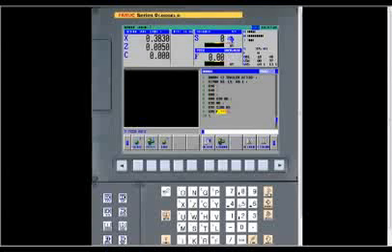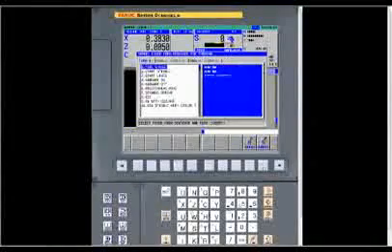Now this feed rate, you would think you wouldn't have to do this because you're going to put a feed rate in the cycle. But if you don't put a feed rate here, occasionally, if the control does not pick up a default feed rate when you go to run the program, you'll get an alarm saying no feed rate commanded. So that's why I always try to put this in my start line, just to keep you from getting an alarm further down the line. It makes it very helpful to do this at the beginning. So we'll say 0.01, alter again. So now we have our start line, then we go back to our fixed form.